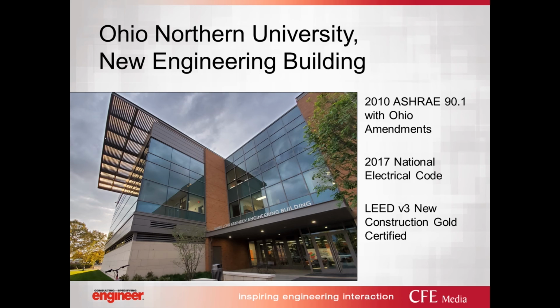Well, thanks, Barrett. So the first case study we want to talk about is Ohio Northern University. It's a new engineering building. What I listed here were the design requirements: ASHRAE 90.1 2010 with Ohio amendments, the 2017 NEC, and LEED version 3 new construction. It ended up being gold certified. Now, we had a conflict between LEED and ASHRAE 90.1 2010 with Ohio amendments on this project, where Ohio allows the exemption for the 50% receptacle control, but LEED requires it.